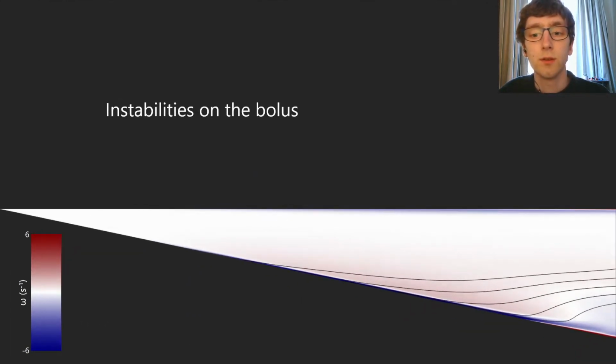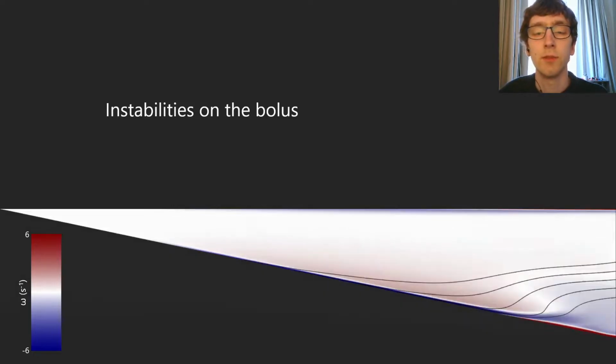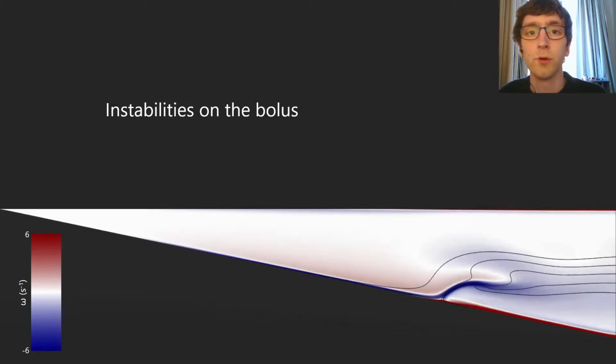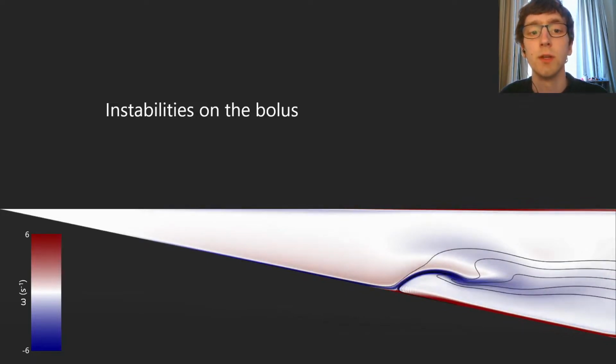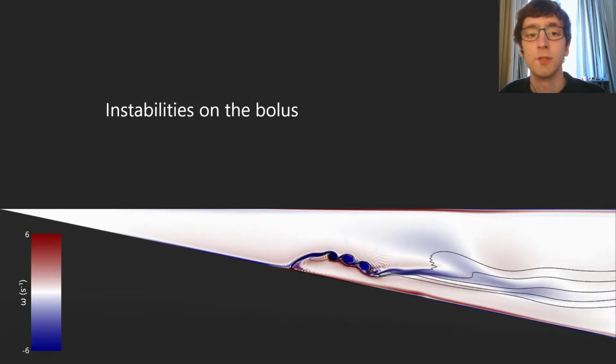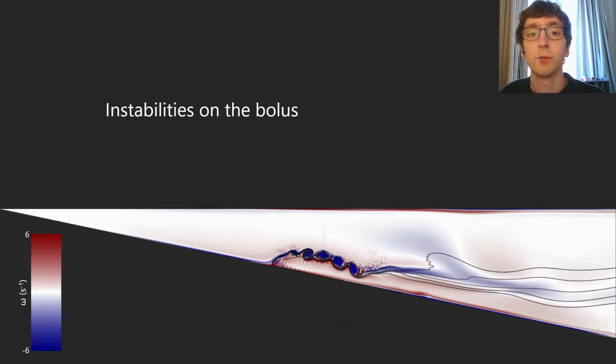So, looking at this, we have again the same wave steepness and slope steepness as we showed earlier for the plunging and the collapsing forms. The wave comes in and the isopycnals steepen, but as the bolus forms, we get instabilities on the upper surface of it, which form in a train of 4 or 5 Kelvin-Helmholtz instabilities. This is a feature which will cause a lot of mixing compared to the surging breakers we saw in three-layer stratification, or even the same surges we saw in the same stratification at lower wave steepnesses.